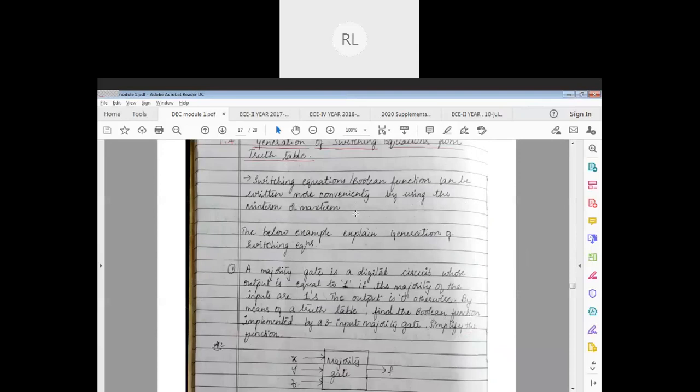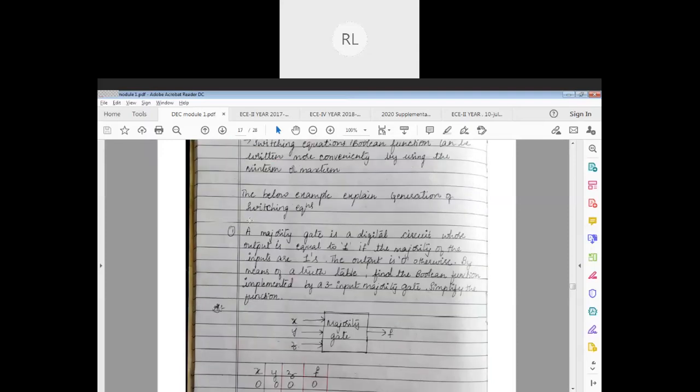Minterms with lowercase m, maxterms with uppercase M, and I'm picking up zeros wherever there are zeros at my output function f, for whatever is my input combination, xyz or abc or jkl, whatever can be your input combination. I am interested in looking into my output function, which is f. Summation is used for minterms, and pi is used for maxterms. These things should always be in your mind.